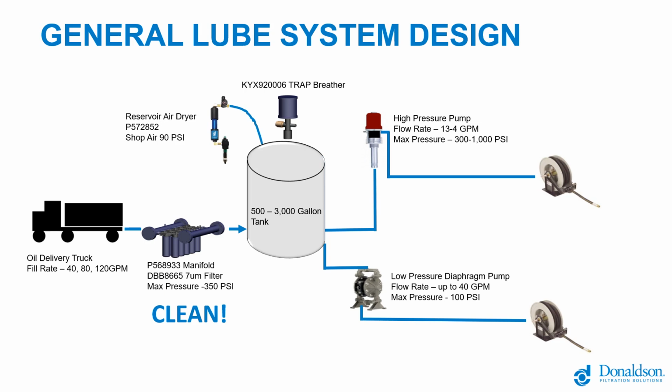and perhaps, since you're going to have compressed air to run one of the dispenser side pumps anyway, purge the headspace of that tank with dry air to prevent any condensation. Condensation building up in the top of that headspace runs down and reacts with the additive package in the oil and tends to drop solids. Purging maintains that tank clean and dry. As that new oil comes in, it stays there clean and dry.